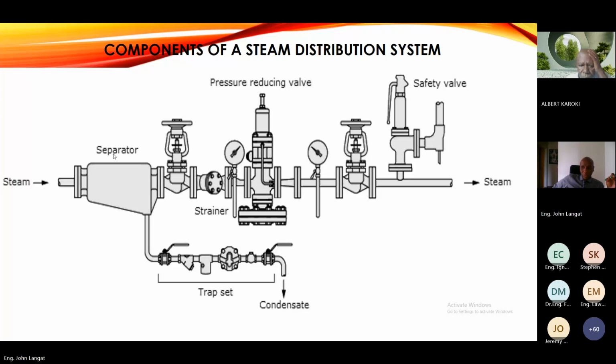You remember when we talked of the level of water in a steam boiler, I should have mentioned that a high level of water in the steam boiler, apart from reducing the amount of space that you use to accumulate steam, will also cause a lot of carryover along your steam line. Of course, that notwithstanding, even if you have the appropriate level, you still carry over some water into the steam line, which is not recommended.